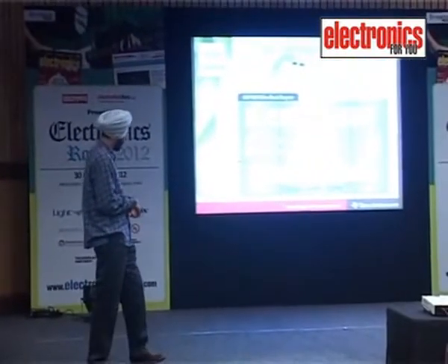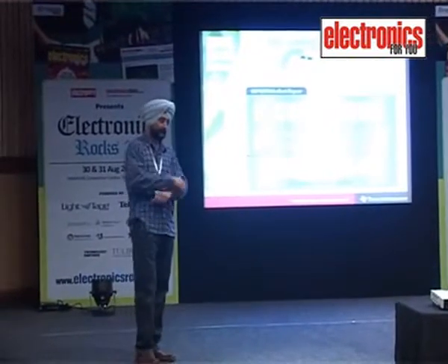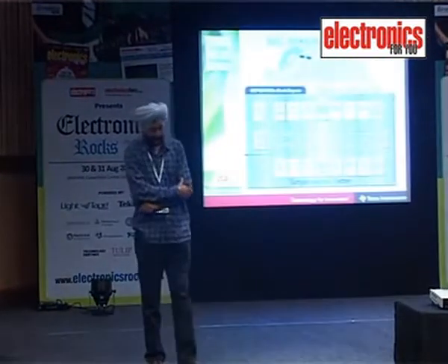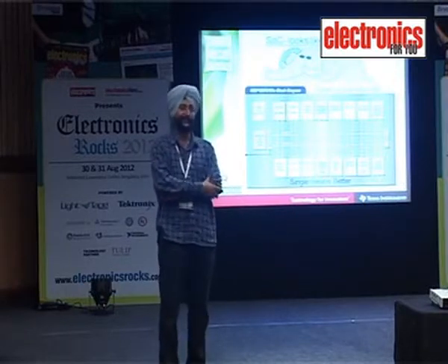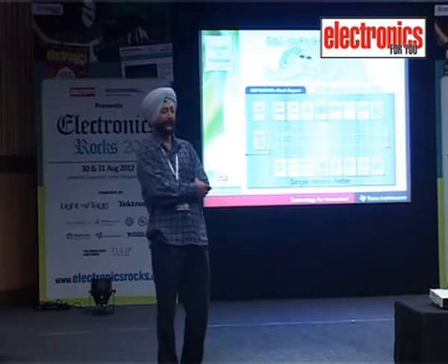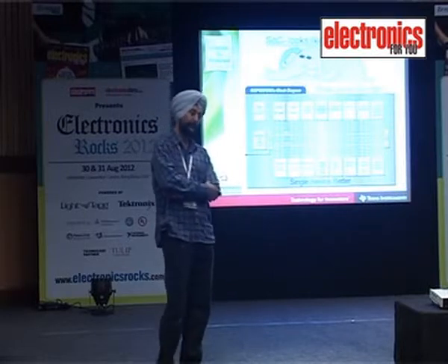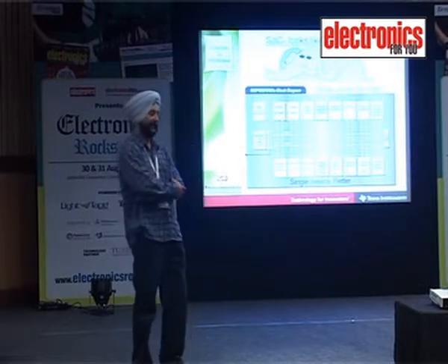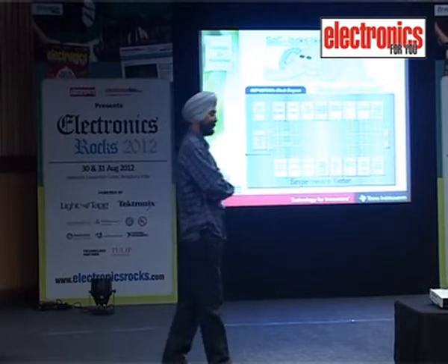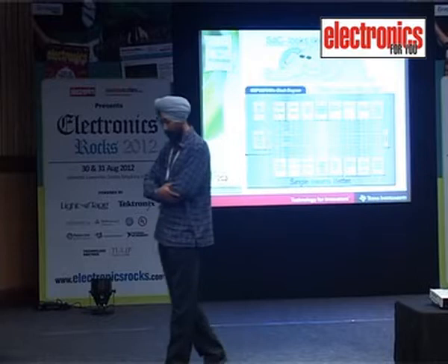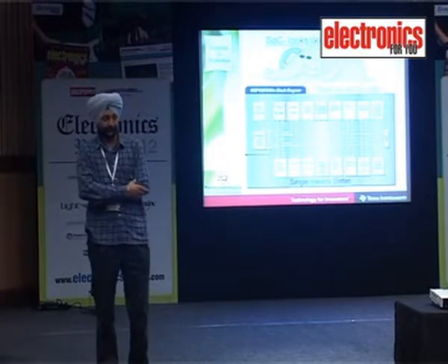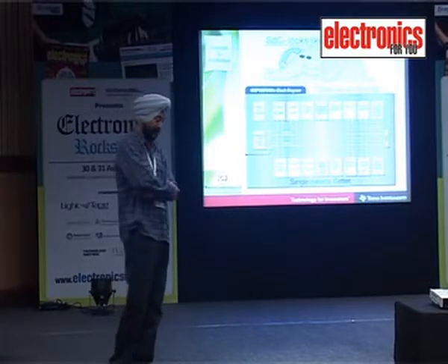And two timers, timer A and timer B. So these two timers can select your internal clocks. As you know, we have multiple clocks. We have a built-in clock, that's a DCO, digital controlled oscillator. External crystal, that's a 32 kilohertz slow speed clock. And again, high speed clock, 8 megahertz, 16 megahertz up to 25 megahertz. Now, why we have multiple clocks here? As you know, this chip is an ultra low power chip.